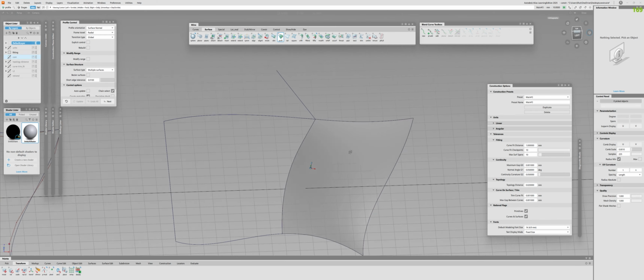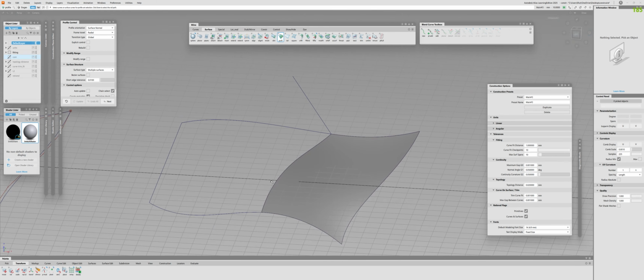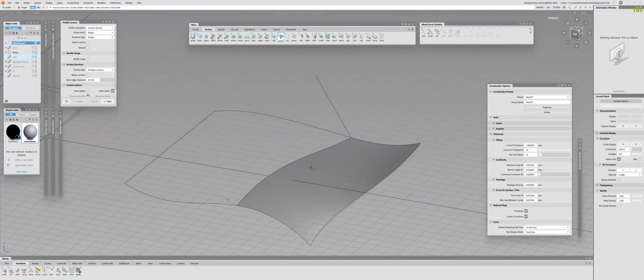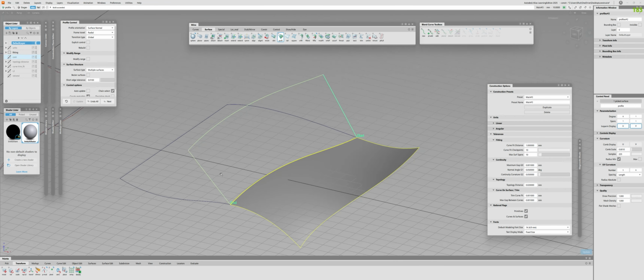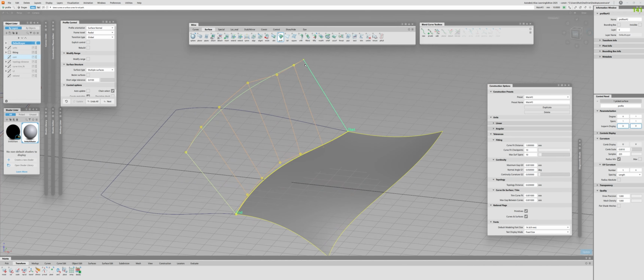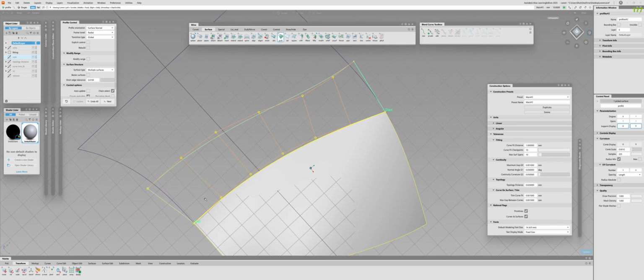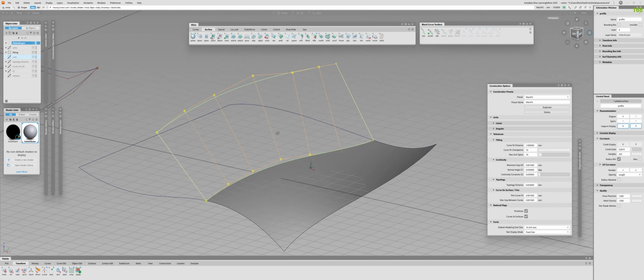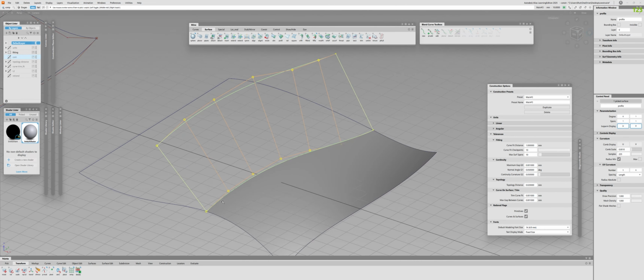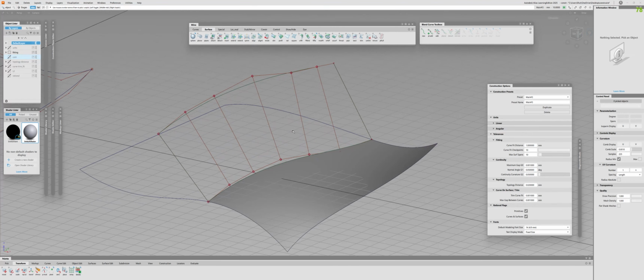So I will go to my profile tool and just create the profile along this trimmed complex line. I select this and click build. Now, as you can see, Alias has little to no problems building this, and actually it's very, very clean. It's only 6 degrees. You see, only 6 degrees. It's very accurate. All nice, right?